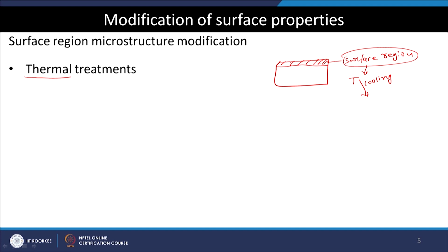You all know about phase transformations. If not, then I would say that becomes a basic requirement to follow these kinds of courses. So, you have a steel which has a certain carbon content, a medium carbon steel for example, and somebody has made a component, and this component has been heated, cooled and then tempered. That means, you have produced martensite which will be very hard, and then you tempered it so that it has optimal values of toughness and tensile strength.